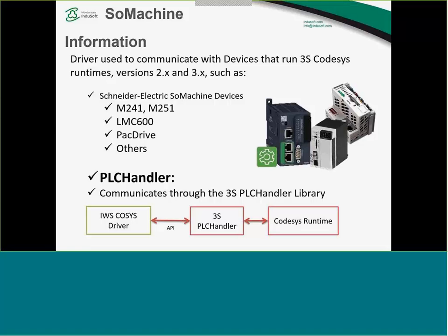The way it works is that we wrote a driver for Codesys, and Codesys is the core that runs in all these devices. The PLC part of all these devices is Codesys. And Codesys has one library called PLC Handler. So we programmed our Codesys driver to use this API from 3S, the makers of Codesys, called PLC Handler. And through the PLC Handler, we get to the Codesys runtime that is actually running inside.